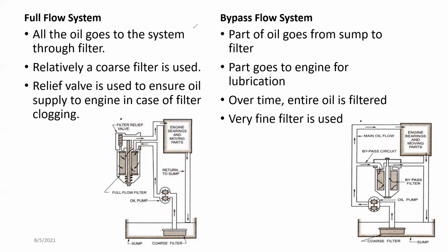Both types of filters are very effective, but as you would guess, the full flow system is a bit more effective. But in the full flow system, the pump has to maintain higher pressures in order to push all the fluid through the filter and maintain the pressure inside the whole system. In the other system, it can get away with a little bit lower pressures.